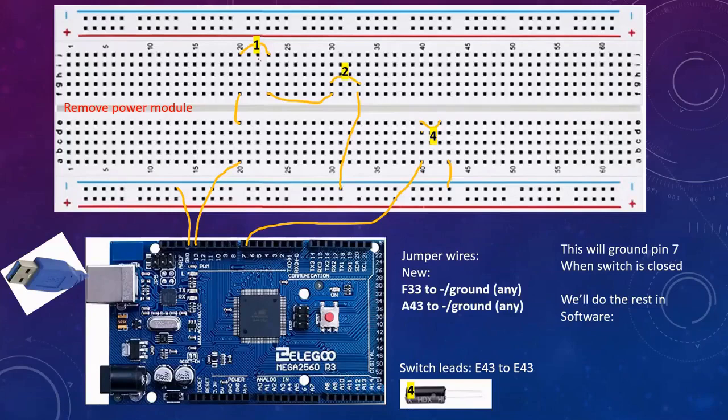And so you'd have to build some kind of circuit outside on the breadboard that would pull the pin up or down depending on what you want to do with it. In this case, Arduinos have a built-in pull-up option for their digital inputs.